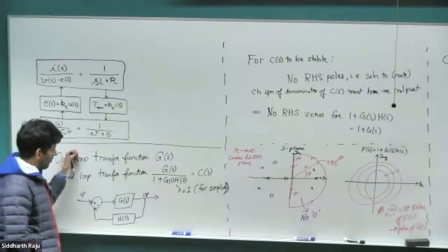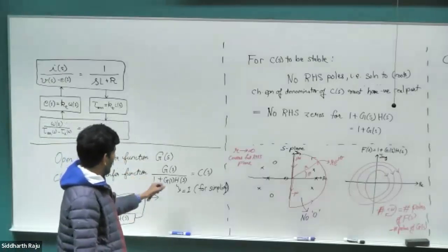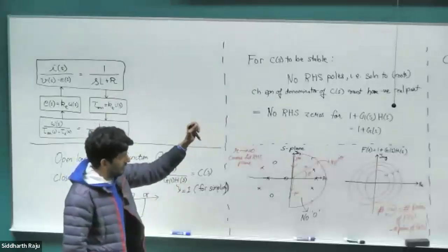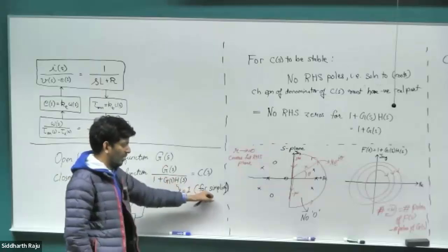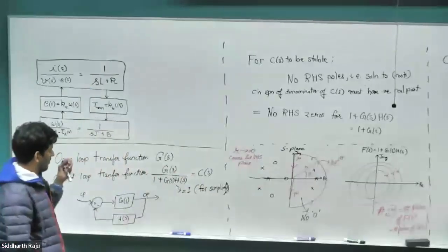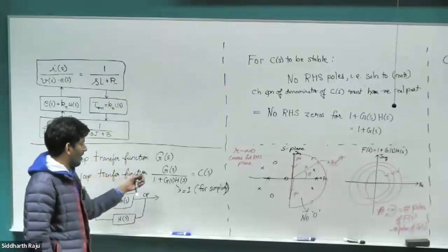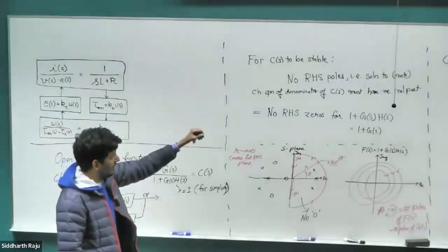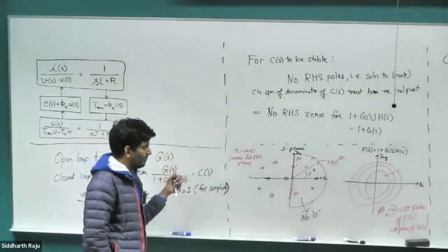And then once you have the open loop transfer function, we figure out how to get the closed loop transfer function. For this lecture, in some places I put H of S and in some places I don't. That is somewhat intentional. We are going to assume H of S is 1 for simplicity. Even if we have some kind of sensor with some sensor gain, that can be quite easily modeled. But wherever I say G of S, it's really G of S H of S. I've just dropped the H of S term, assuming it's 1.